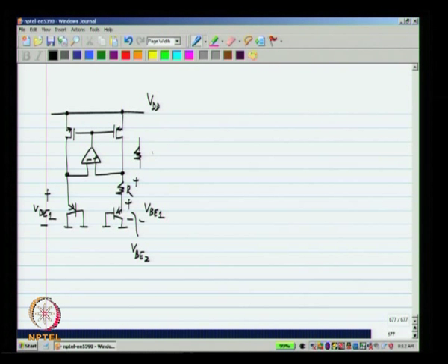So, this is R and that is R1. If we place this resistor in this branch, we get VBE1 plus a PTAT voltage and the final output is the band gap voltage. So all we have to do is to add VBE to this PTAT voltage.